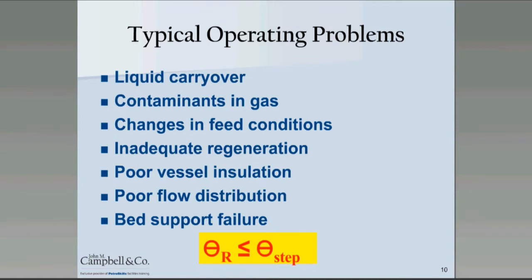Liquid carryover. To avoid liquid carryover, get a good inlet filter separator. In my personal experience, over 80% of troubleshooting can be traced to a poorly performing inlet separator. A good inlet filter separator will solve the majority of your operating problems. So make sure you have a good inlet filter separator, that it is not undersized because your gas production has increased over the years. Check your low points.